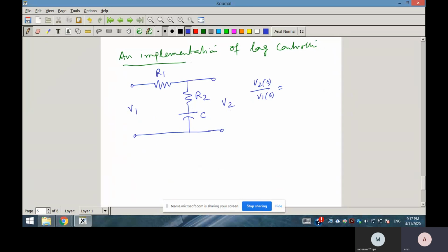So what is the current through it? Current through this loop will be V1 divided by R1 plus R2 plus 1 by CS. So what is the voltage then? This voltage is R2 plus 1 by CS into that current. What is the current? Sorry, current was...